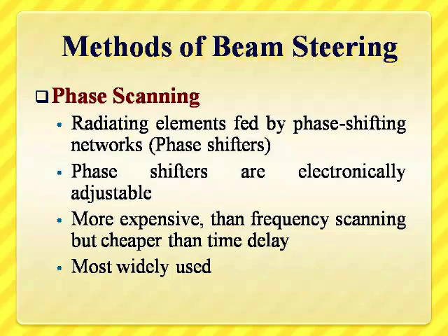But they are most widely used because of the ease of operation. By sending a computer control, we can set these 3 or 4 bit phase shifters very easily to the required value, and hence the operation can be completely computer controlled to get the beam pointing to different directions.